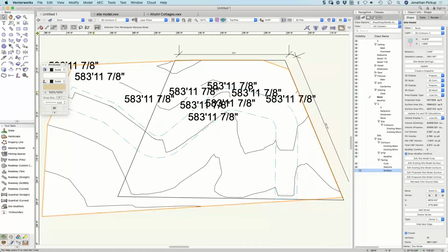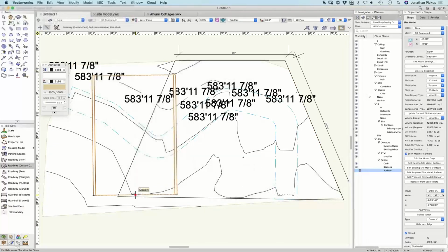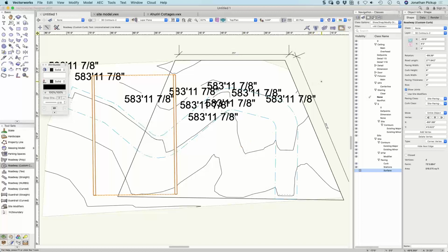Cut and fill calculations, I've answered that. Yes, I've answered that. How to create roads, footpath. Yeah, I think I've done that. I've done that partly, Flavio. What I haven't done is the custom curve, which I quite like. But the custom curve goes in one direction. The slope is going in one way. So once you've done that slope, you can't make that slope follow the contours.